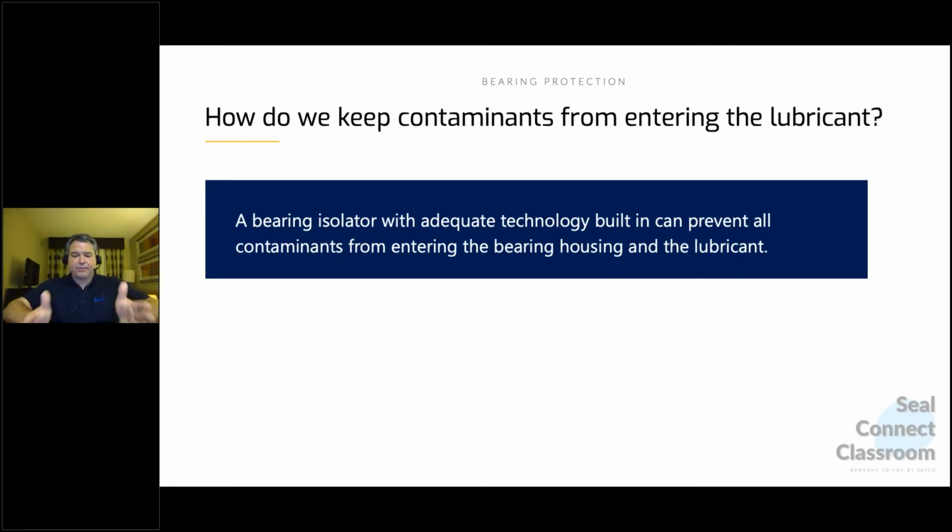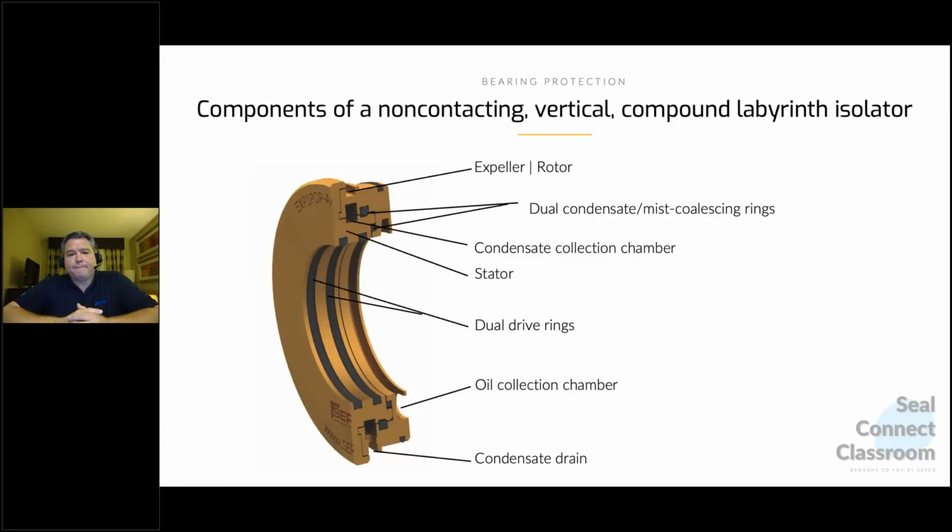Because the machine has a reservoir that has seals, and it has a breather. It has to be able to breathe, and we're going to talk some more about that. In the next slide, I think we have an example. When you think about a breather, it's important to have the right type of breather. If it's open to atmosphere and the machine is cycled out of service, open vents then become a pathway directly into the machine.